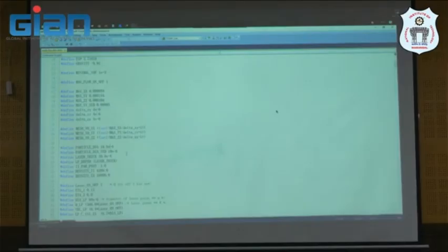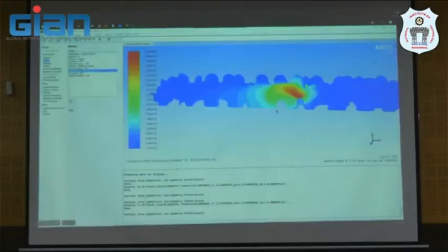But anyway, it's about right. It's in the order of 5 to 10. It depends on how big your domain is. But at the moment, for conventional CFD like this, we do not tend to apply adaptive mesh because it would be so problematic. But now people try to use this for extremely complicated, detailed dynamics that they want to know. But leave it for another matter, that's related to more computational technique.